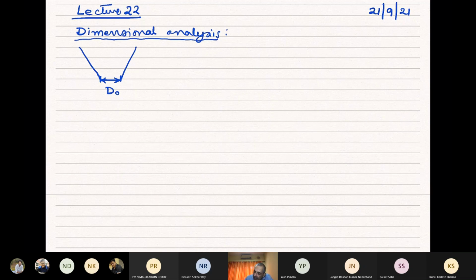we'll see that the velocity at the exit should be proportional to... If it only depends on d0, then the only other way we can make it dimensionless is to multiply it by g times d0. So velocity should be equal to the square root of g d0, correct?